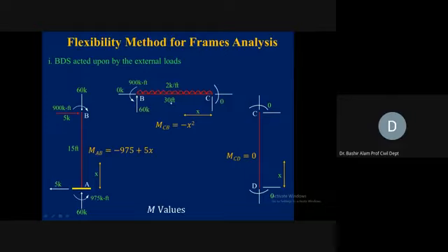That's 2 times 30 divided by 2, which is 30. If we put 30 here in the vertical direction, then it has to be in equilibrium to the right of this joint C. So if it is upward here, it will become downward. How are we going to balance this at joint D, because at D we don't have any support? So this 2 kip per foot cannot travel to the right where we have joint C. It has to be balanced by B only.